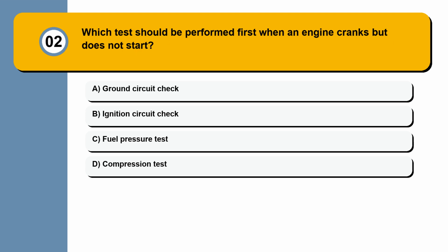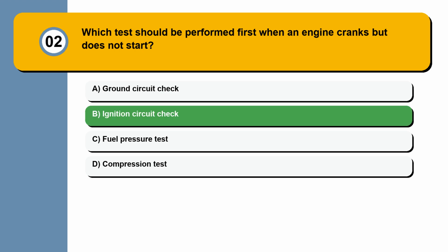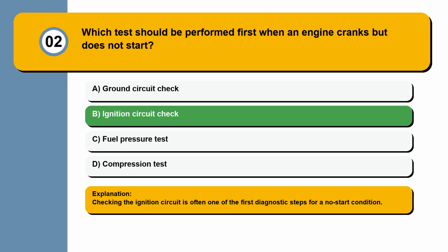Question 2. Which test should be performed first when an engine cranks but does not start? Ground circuit check, ignition circuit check, fuel pressure test, compression test. Checking the ignition circuit is often one of the first diagnostic steps for a no-start condition.